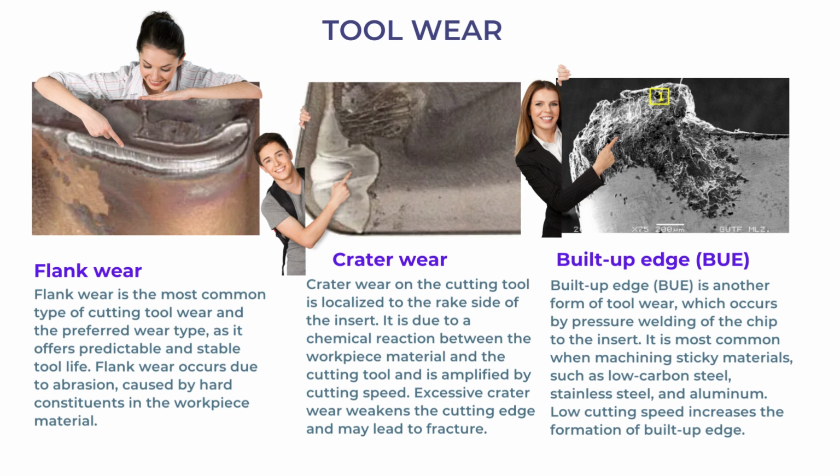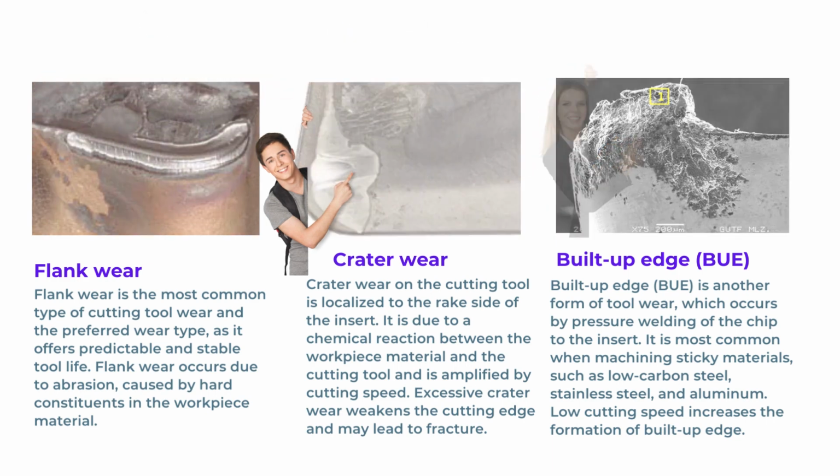Built-up edge consists of welded materials onto the insert by pressure. This type of wear is very frequent when machining sticky materials such as low-carbon steels, stainless steels, and aluminum. A low cutting speed increases the built-up edge.